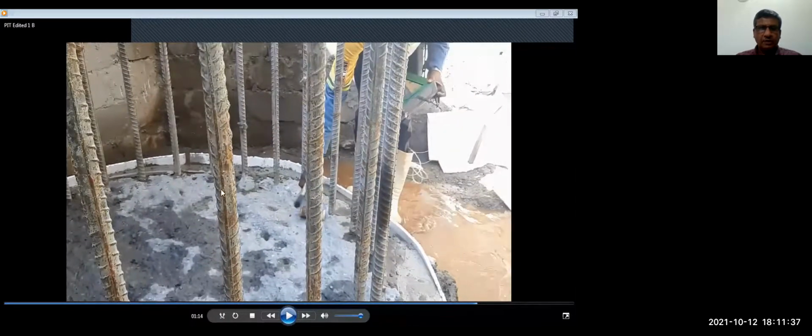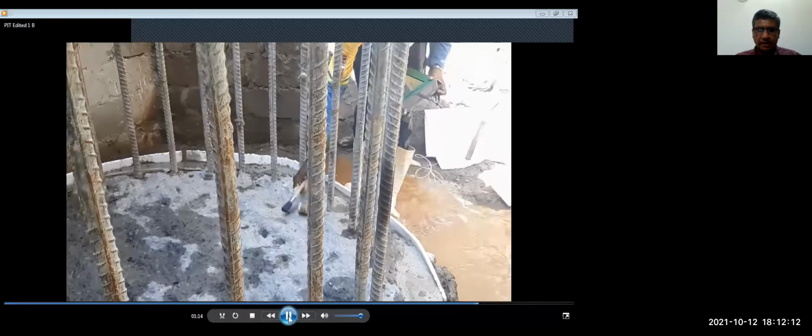So a few points I would like to mention here. The pile, you have to remove the contaminated concrete and come to a level where you have good quality concrete, and this is done right around the pile, looking at the integrity of the pile. So here we install a small accelerometer, and that can be removed, and we also apply a small hammer blow. And so data is collected here. You can see the data collected later.